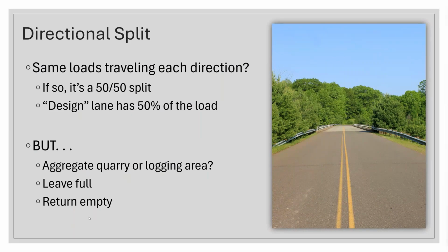But in some of those areas with logging operations, quarries, chicken houses, all that kind of stuff, or it could even be what is the garbage truck route? When are they loaded the heaviest? That could actually have some impact as they go through their routes. So think about that. And if we don't have everything even, then I don't need to divide this 50-50. I need to give preference to that heavier side, and that's how I need to do the design.